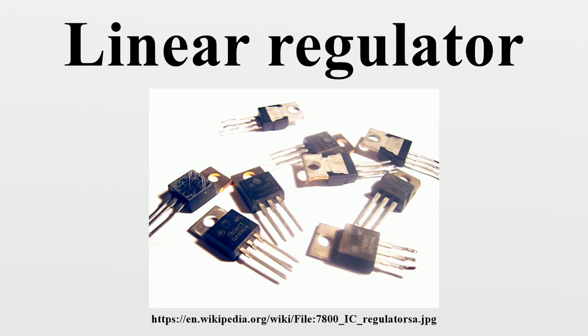This regulator is often used as a pre-regulator in more advanced series voltage regulator circuits. The circuit is readily made adjustable by adding a potentiometer across the Zener, moving the transistor base connection from the top of the Zener to the pot wiper. It may be made step adjustable by switching in different Zeners. Finally, it is occasionally made micro-adjustable by adding a low-value pot in series with the Zener. This allows a little voltage adjustment, but degrades regulation.